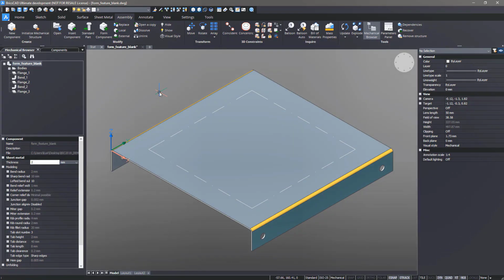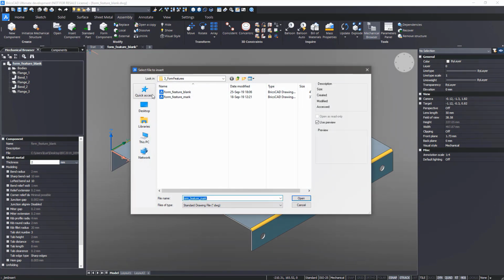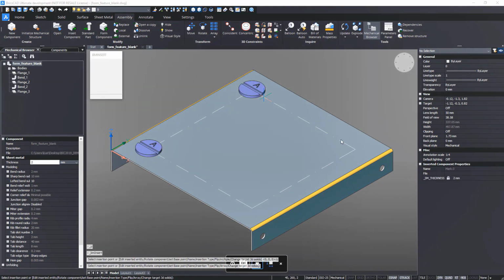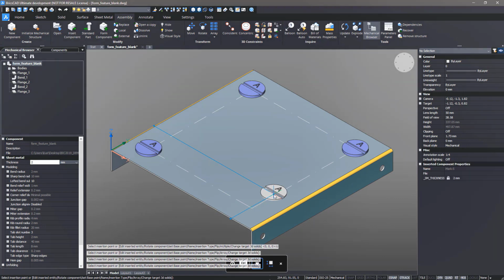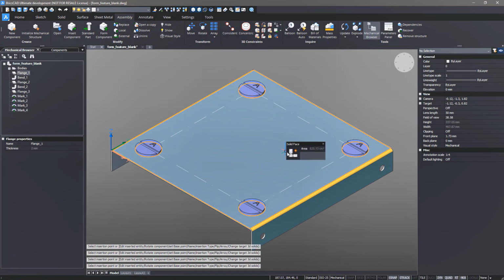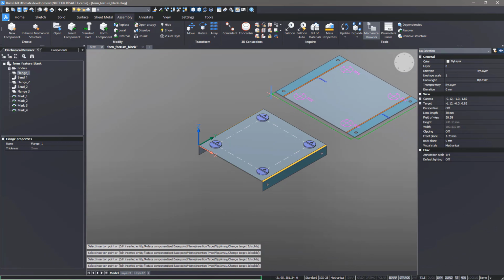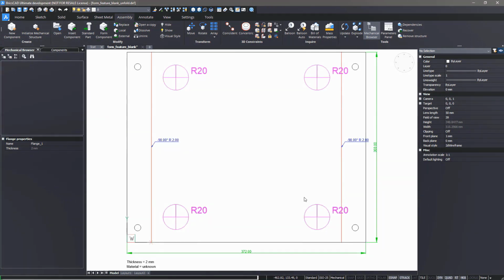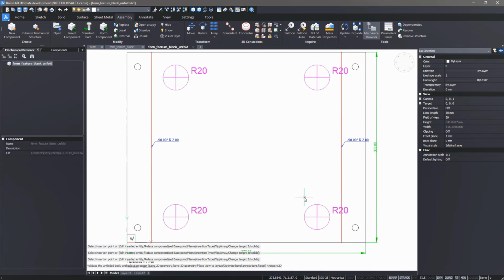Here is a blank solid, and we will insert a custom feature which we are not going to produce by forming. Instead we rather cut some hole and make welding. But we want to propagate this information to DXF. This is the preview, and this is the resulting DXF file. So the tip is that unless your geometry will be produced by forming, you can use this mechanism in order to propagate your annotations onto the DXF.